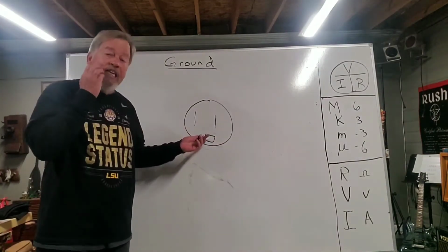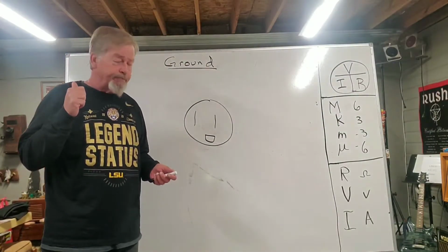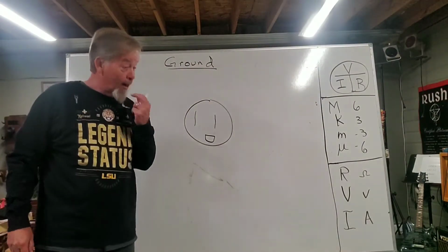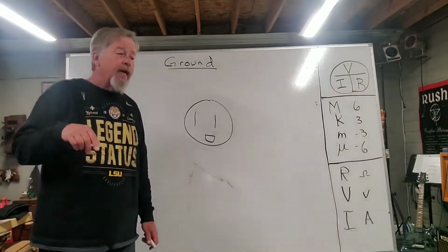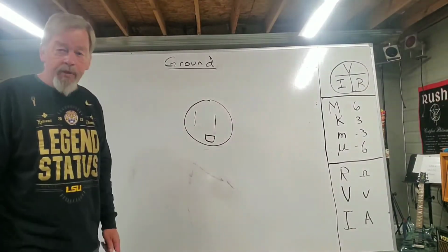Now, this ground is actually connected to a wire that goes out by your meter pan. If you go look at your meter pan, you'll see a bare copper wire coming down and attaching to a little metal post. Well, that metal post is down in the ground, probably about 6 feet. And so that connection puts ground potential at this point on the receptacles. Now, what good is that?